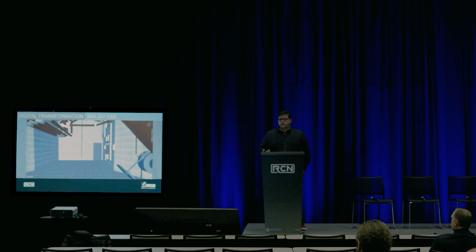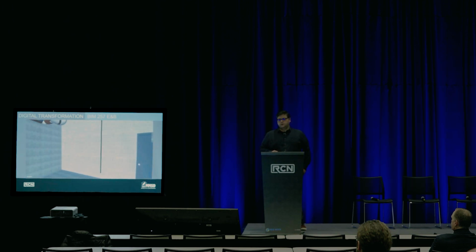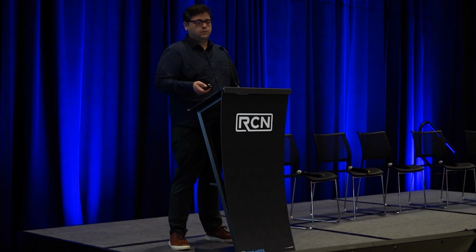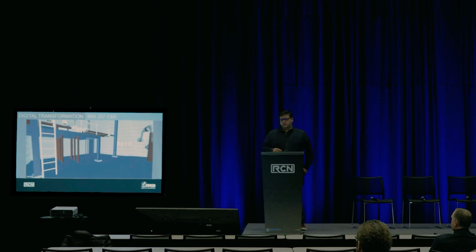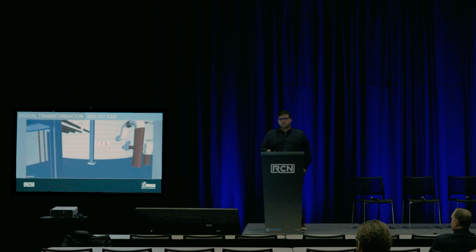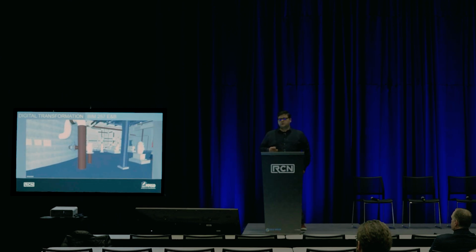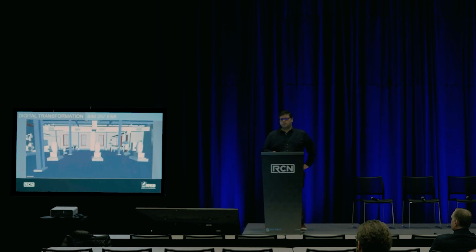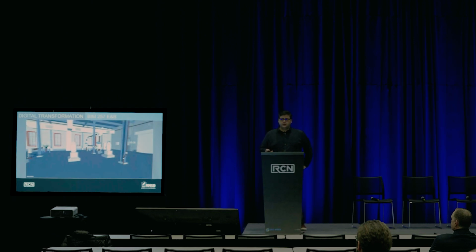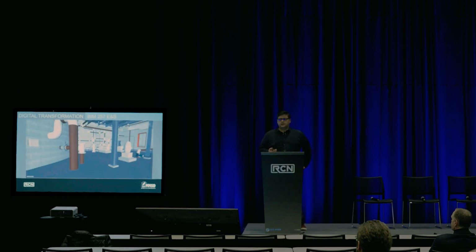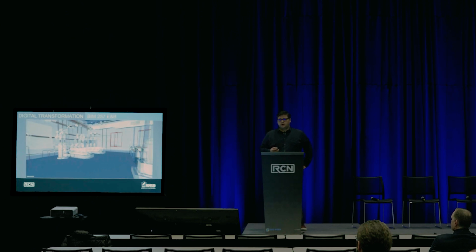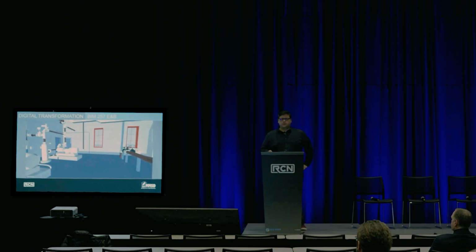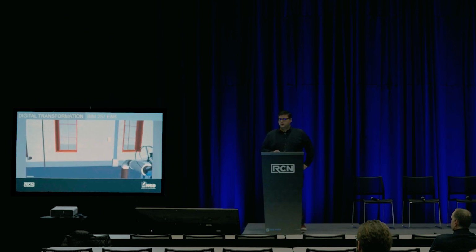And again, with this model, you can just see how complex these areas can be. Here we go. That's the first floor of the equalization and blend facility. We modeled this with a high level of development, which is level of detail plus level of information. You can see a lot of the structural and architectural components are a lower level of detail, LOD 100, where a lot of the assets that we care a lot more about and want to track more are LOD 350 to 500, just depending on what they are.